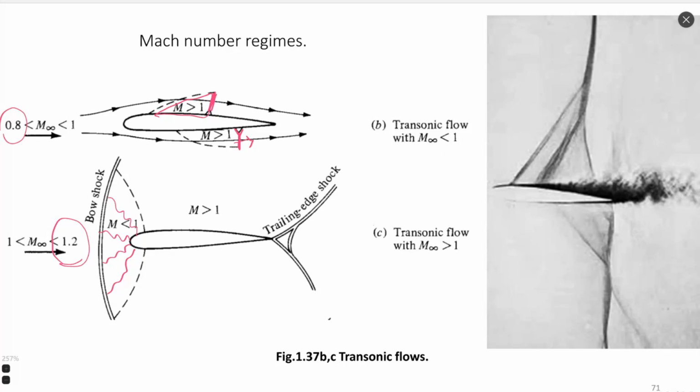When they accumulate, they create a pressure gradient, and the flow starts to stop because it's a pressure gradient that acts against the flow. So the flow starts to stop and such a subsonic region appears. Then all pressure waves are stopped in some specific position, which forms this shock wave, the bow shock wave. So the bow shock wave is an accumulation of a big number of pressure waves that were generated by the body, and they go against the flow.